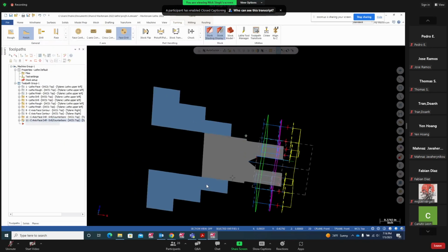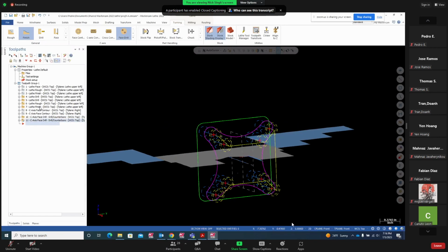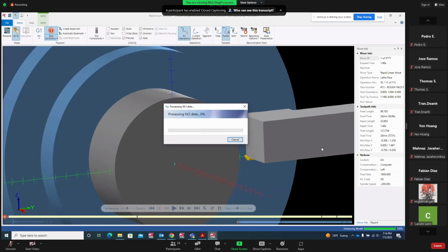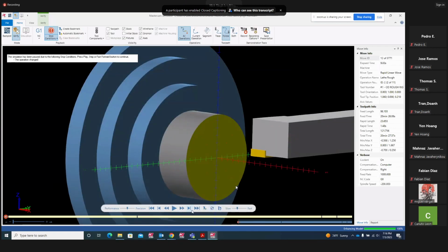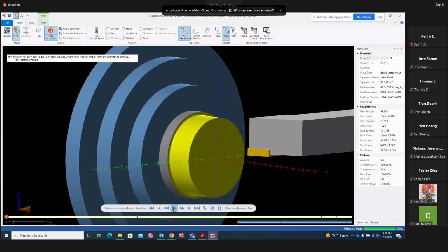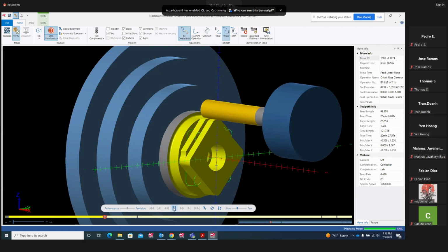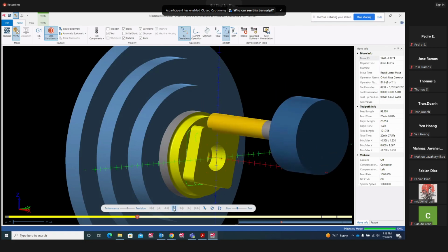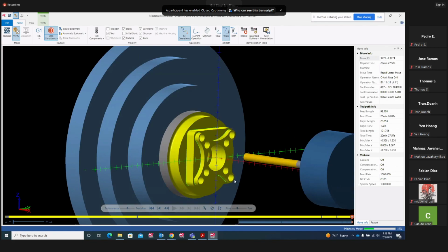There are my drilled holes. I'm going to run this entire part. Face it. Go to rough, finish, drill, spot drill, and bore it, finish. And here comes my face contour, another face contour, center drill, and your drill. There we go.